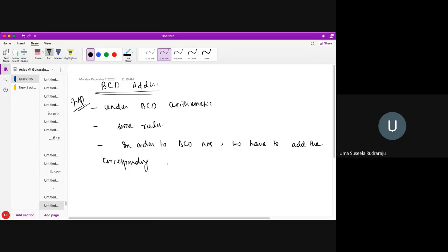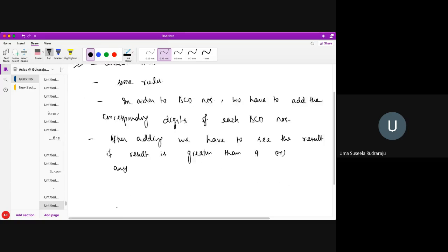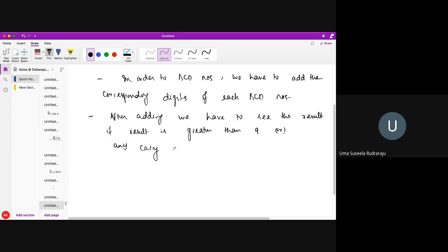After adding, we have to check the result carefully. If the result is greater than 9, or any carry arises, then the result is said to be an invalid BCD number.